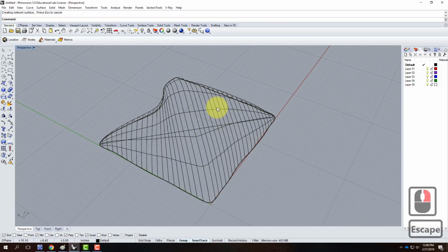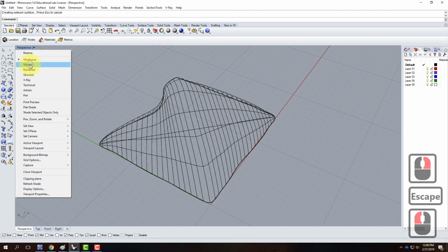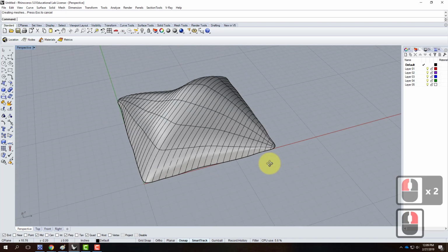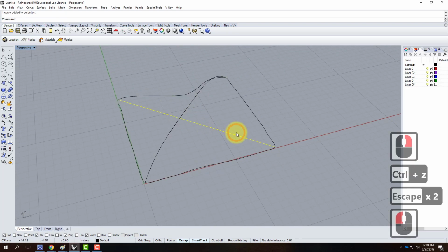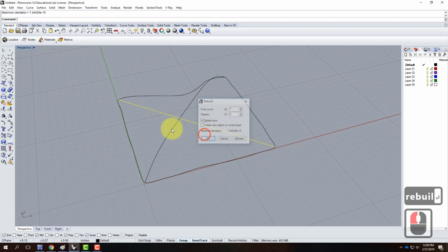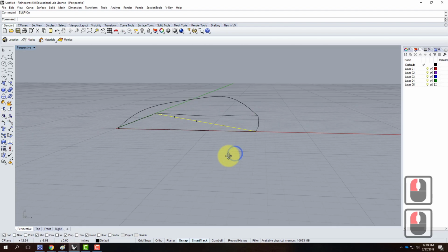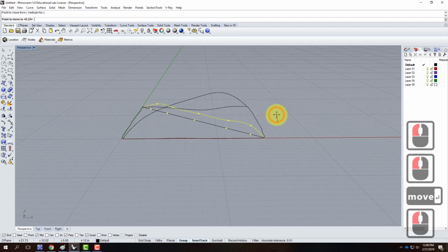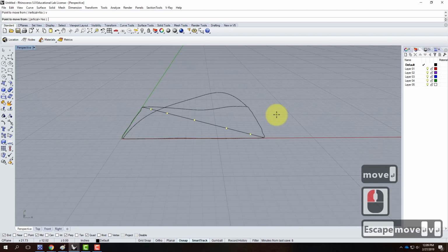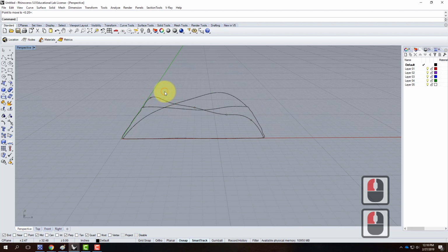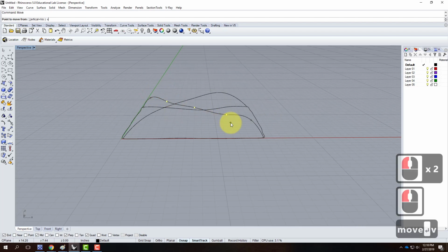So if I wanted to add some more, let me change this into shaded mode so you can see it. If I wanted to add some more definition to this, I could work with this curve. I could rebuild it again, and I could turn my points on. Now I run a risk here, and that is that if I took these curves, let me move them up. Oops. Helps if you type V for vertical. Move these guys up a little bit.